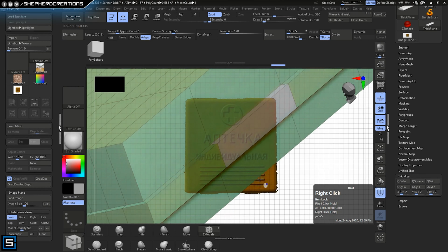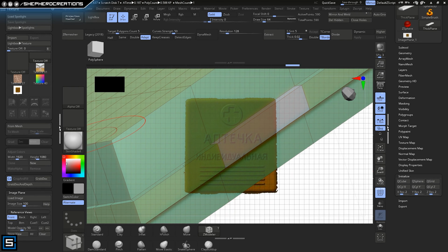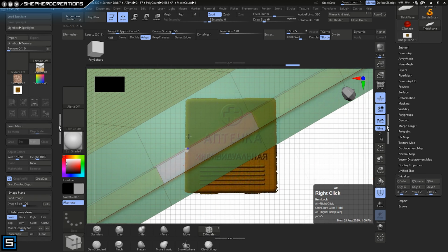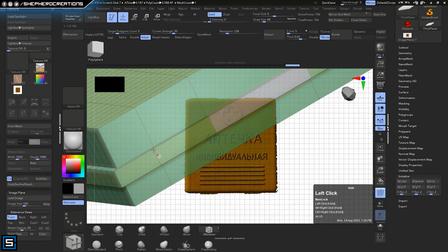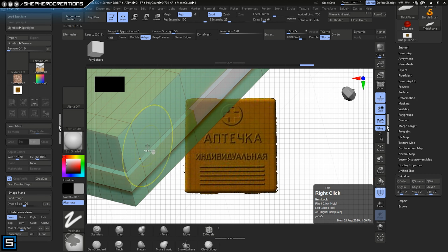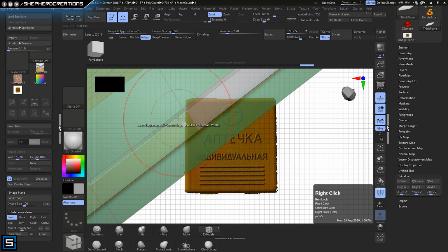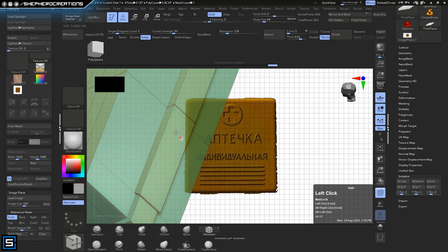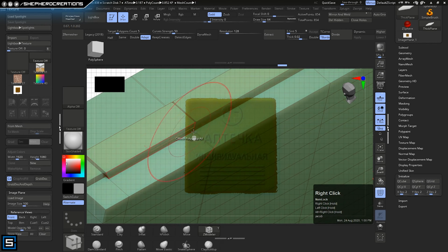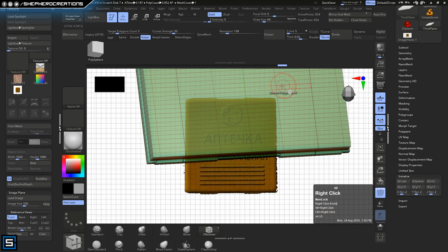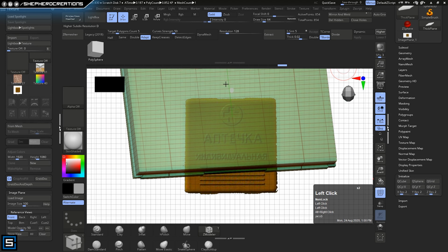Here again, I'm highlighting, and I'm going to left click and hold to drag that out. Looks like I'm going to insert a new line. All I did was hover over a poly loop until it turned white and left click, and that drags a new poly loop line. Now I've got that little gap in between the two selections, and then I left clicked, held, and dragged out using QMesh, and I extruded that even more. That's how you can select different areas.